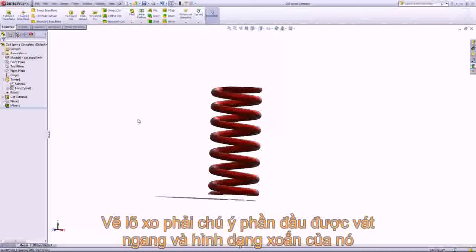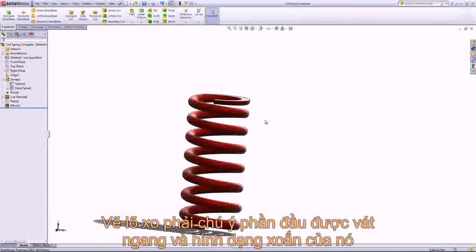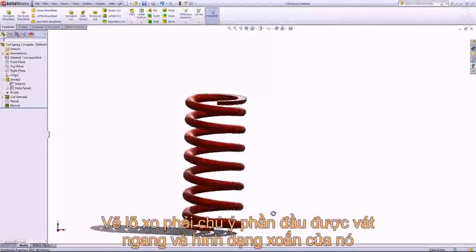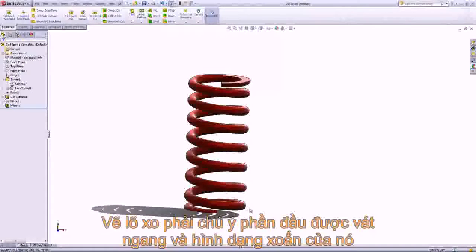Generally, a spring is fairly easy to create in Solidworks, but one question that comes up quite frequently is how to create an automotive spring like this that tapers off at the end and has flat spots on both sides. So we'll be using a variable helix and a swept feature to create this part.